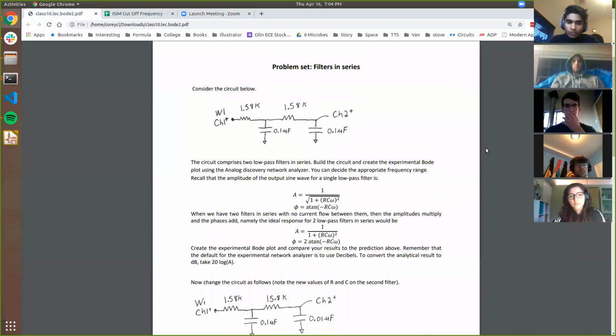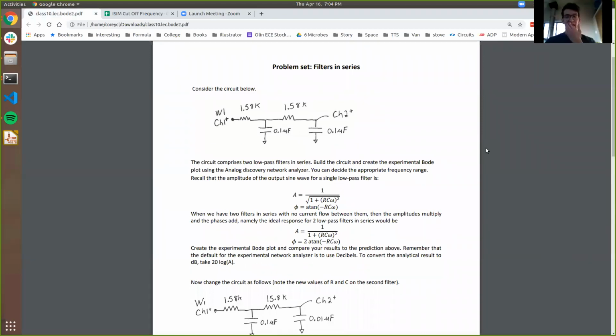ISIM labs. So Brian Story just handed you this lab to do, and it's like 2 in the morning. You really don't want to walk all the way to the lab, so you decide you just want to simulate it in LTspice. You look at the lab, and he's having you run through 2 RC filters. We've all seen an RC filter before, and he's trying to make you do 2 filters in a row, which should theoretically give you twice the filtering capacity. So instead of a slope of -1, for example, it'll be a slope of -2 after the cutoff frequency. That's what we should expect.